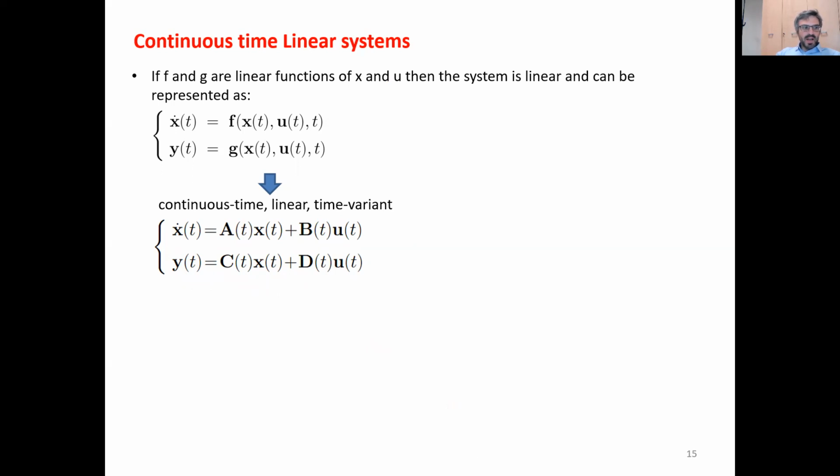So whenever you have a matrix in your dynamics, you're able to represent your dynamics with a matrix product, and you have a linear system. And this is the state transition matrix, B is the input matrix, and C is the output matrix. This one doesn't have a name, it's just a direct mapping between the input and the output, but usually we don't have it.